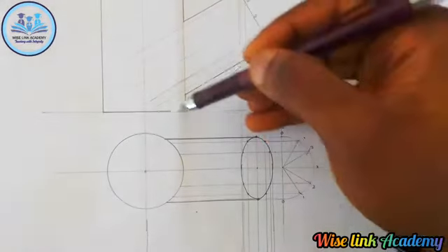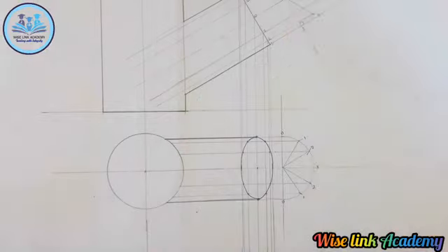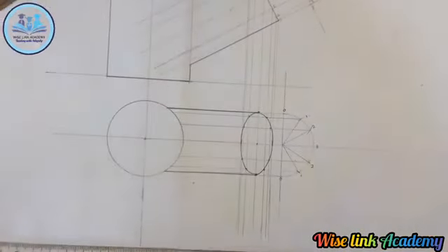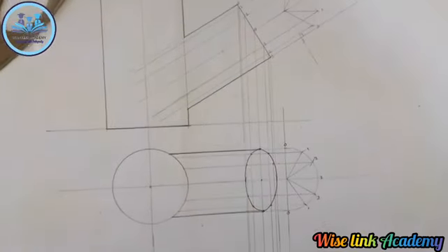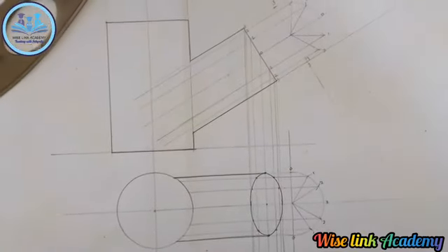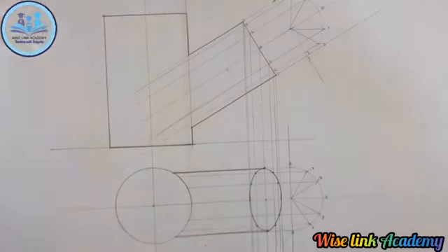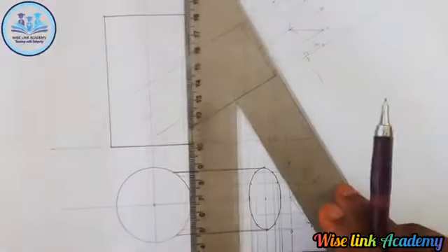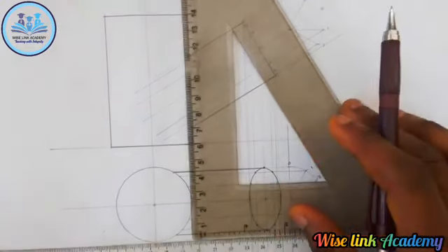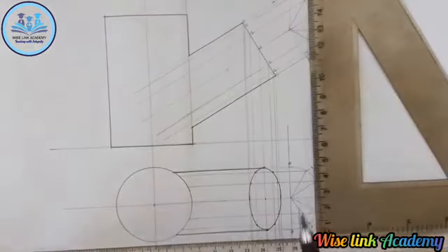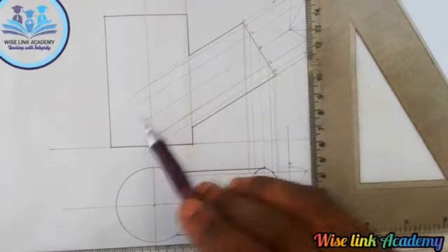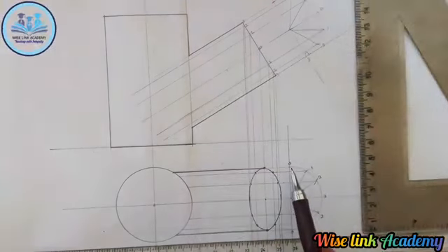If that arc is well fitting, between this cylinder and this cylinder, there will never be water leakage, isn't it? So now let's do that. It is a very simple procedure. Let me show you. You take your set square this way, as you can see, and your T square this way. Let's start with point 0. This is my point 0 here.